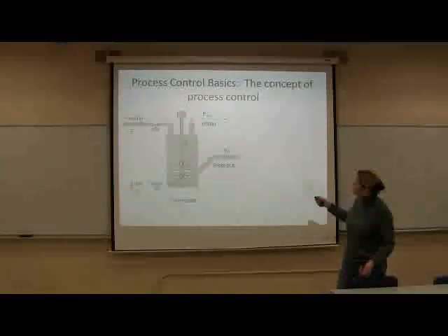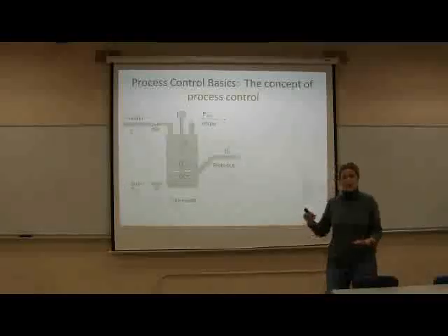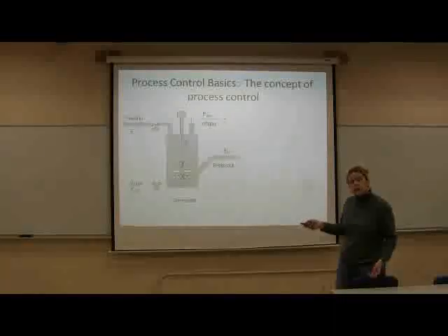And we will be removing off gas that is produced during the fermentation. We need to remove that because if not, we would have an explosion. And we will also monitor the components of that off gas. So let's talk a little bit about controlling this process.